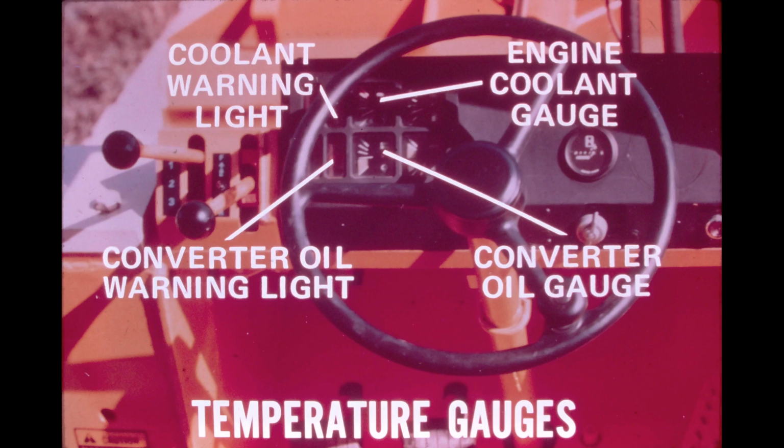High converter temperature is an indication of aerated or contaminated oil, a converter regulator spool not fully opening, or a restricted oil cooler. A low oil supply or converter leakage would show up immediately as a high temperature problem because of the heat produced by slippage and turbulence. Oil lost through leakage at the converter drains directly to the sump instead of going to the cooler where it would ordinarily lose its heat. Oil lost through leakage will reduce the lube supply, resulting in an increase in the heat of friction in the clutch pack shaft assemblies.